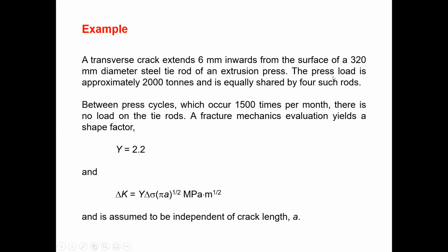The press load is approximately 2,000 tons, and it is equally shared by 4 such rods. There are 4 rods like this, and each will carry this much load.